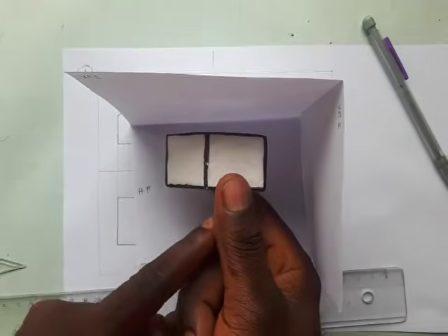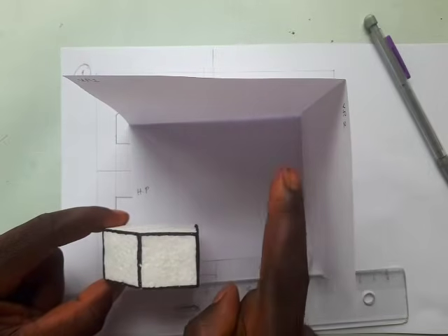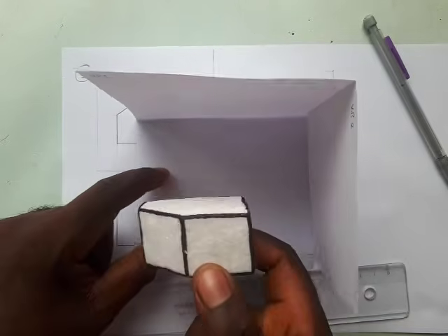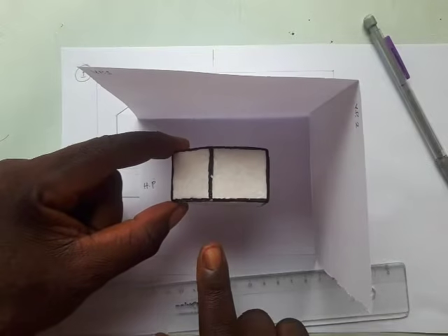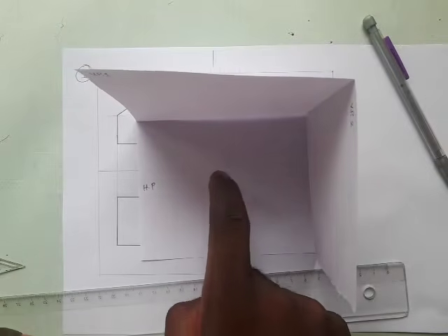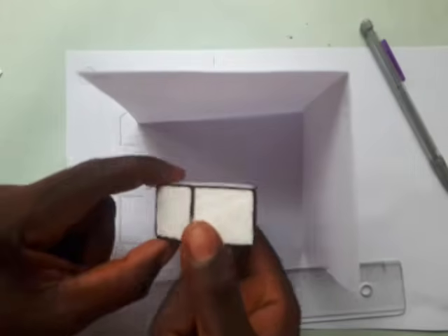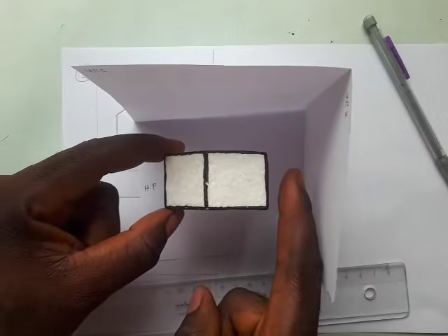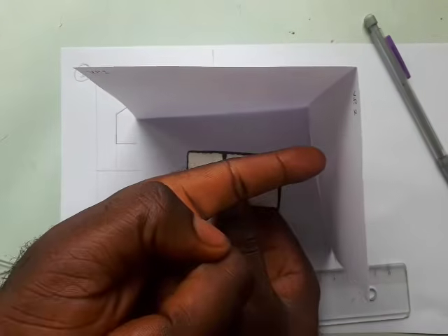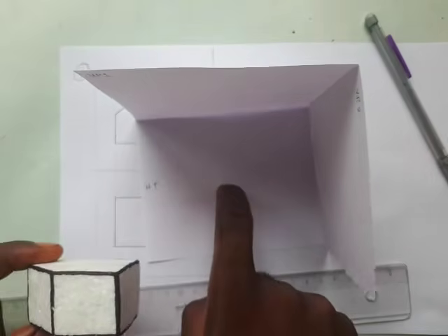So if I move from this point and I come to this other side and view, whatever I see, I would draw it on this other vertical plane here, because this is also a plane. Now if I go back here, this is my initial position, and I move up and I view, whatever I see, I would draw it on this horizontal plane, and that is my plan. So whatever I view from here and draw on this plane is my front elevation. I move from this side and I view, whatever I draw here is my end elevation, the view from here. And I come back here and move to the top and I view, whatever I draw is my plan.